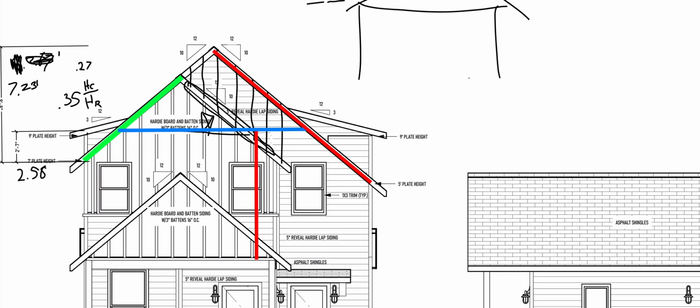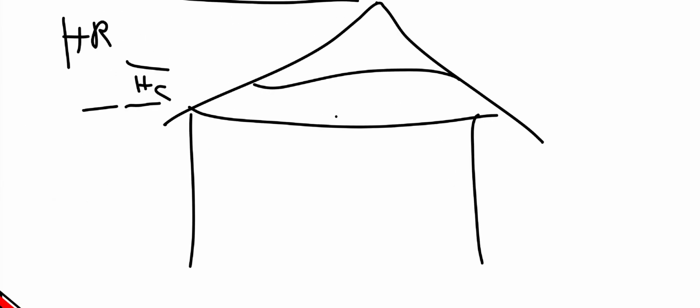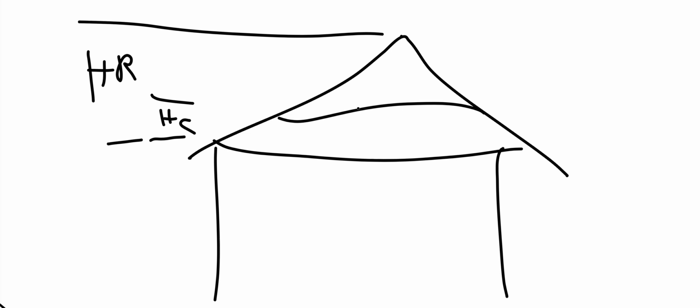Now, I don't have that because what this is assuming is that the ceiling joist right here is holding the same. Let's see how to describe this. The tributary area would be this halfway weight, and the other half goes to the other wall, right? And the roof is the same thing. The roof is assuming that whatever this span is, I'm holding all that ceiling weight.